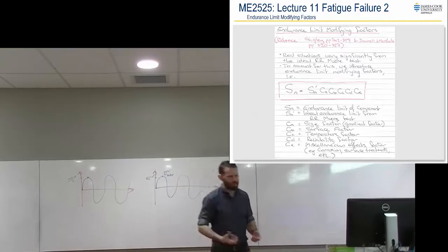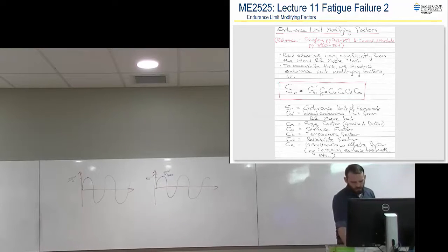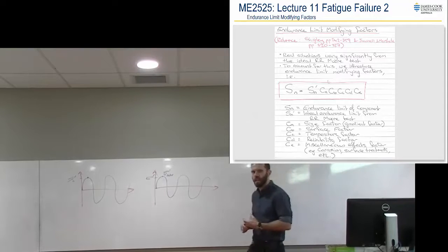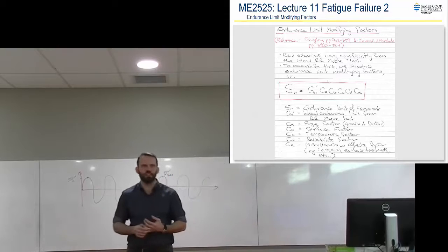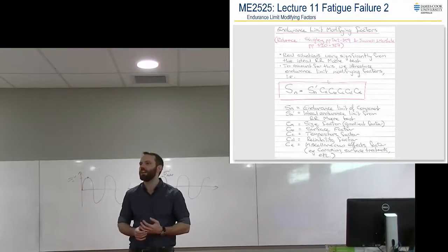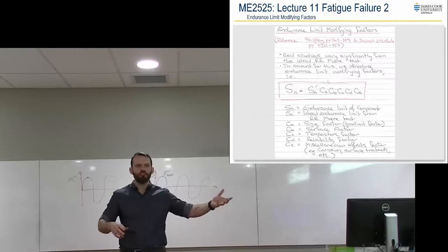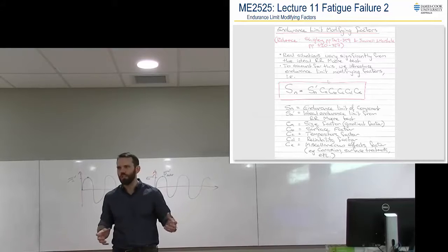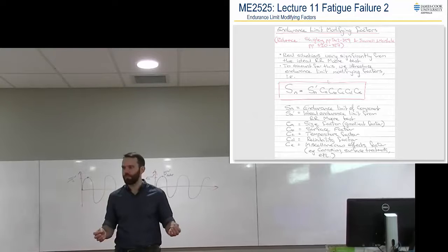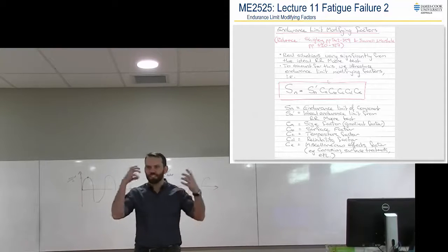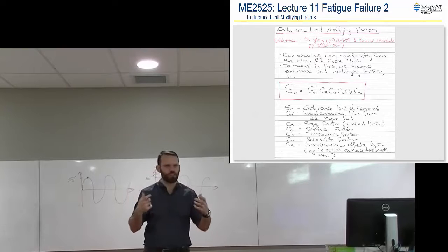Decrease. Yeah. So, if you look at this number, and you get a modifying factor that increases our endurance limit, is that correct? No. You shouldn't be increasing an endurance limit unless you're like coating it in titanium or something, and we don't have factors for that. Alright? If you get something that's 0.5, alright, 0.5 is decreasing it, good. If you get something that's 4.8, increasing it, bad. You've screwed something up. Okay? So this is our rational thought checks and balances that we're talking about, right?